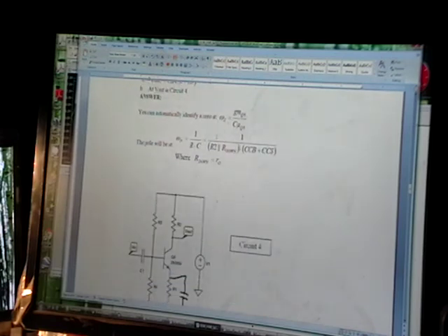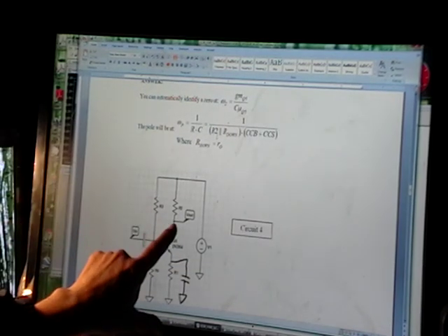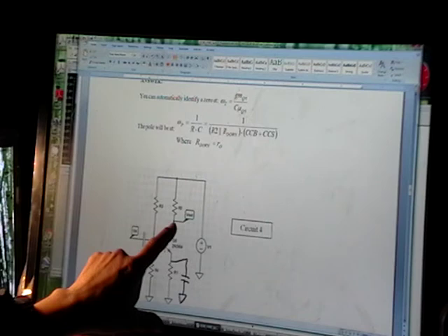Okay, at V out, if you've seen the video, you've seen that you get a zero when you're at the output, and you can just memorize that it's GM over C mu. That's the only one we're going to see, GM over C mu.